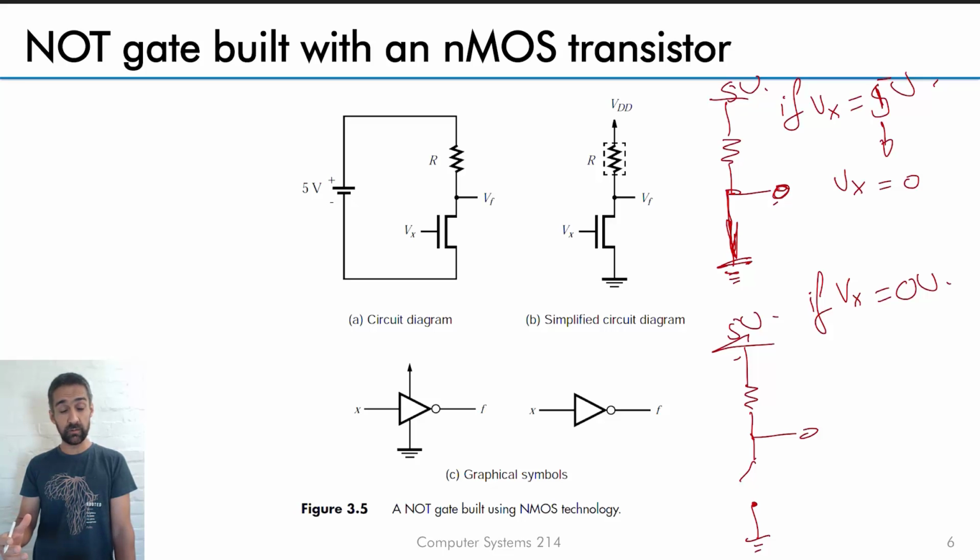Now this is something that you'll come across often in e-design, in computer systems, everywhere, so be sure that you get this. The effect of that resistor is, in the case where you have this setup, that resistor provides a voltage drop. So current flows through it, it gives a voltage drop across there, and it allows this to be 0 because it's touching 0.